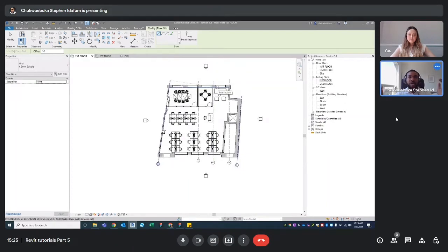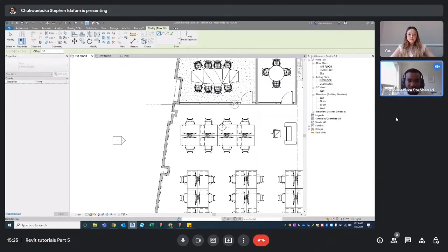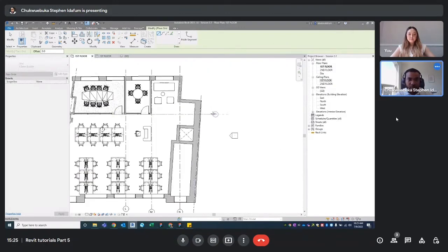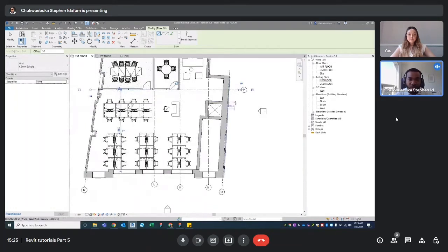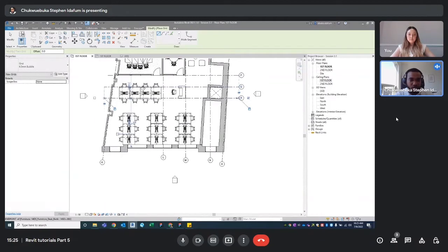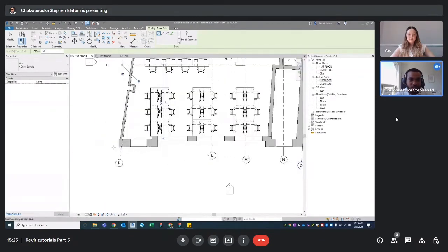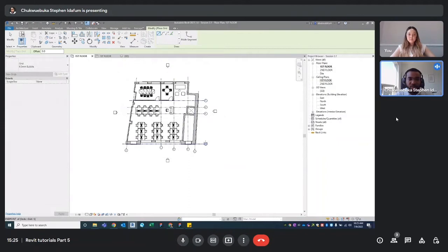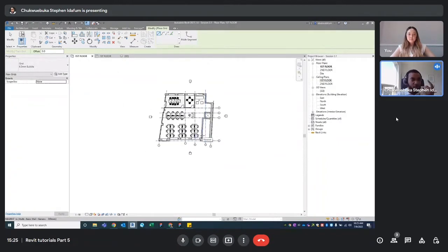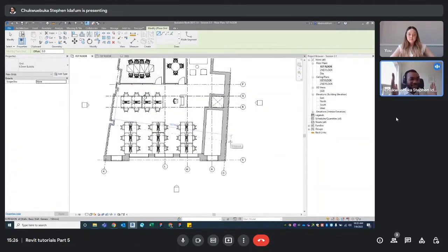So it will go from the exterior wall to the major interior walls that are load bearing, and the exterior wall as well. For example, another one will go horizontally like this, through this curtain wall. You get my point. And another one will go through here, just aligned to that. Another one will go through here, just where you have structural elements like walls that intersect, and the final one will go through here. So this is how the normal grids would look, but it looks a bit weird in this video because the walls are angled slightly.